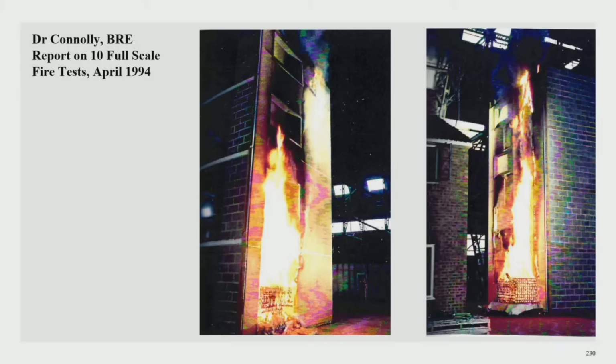Of particular relevance, he concluded that small-scale reaction to fire properties of the cladding materials did not reflect the fire hazard associated with the full-scale cladding system. He concluded too that the provision and nature of fire barriers and cavity width needed to be considered. Finally, he concluded the clear need for full-scale testing of performance and fire for what he termed rational design of cladding systems.